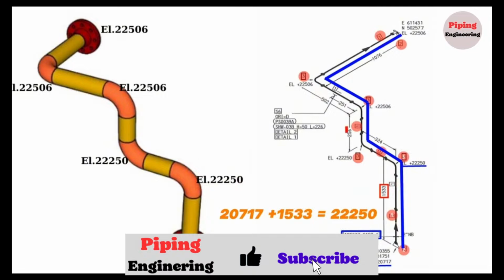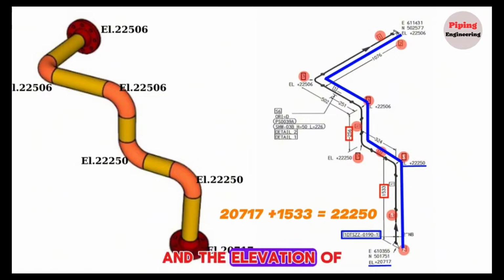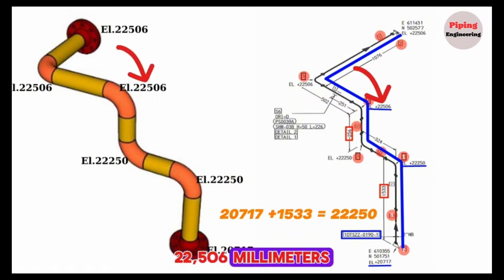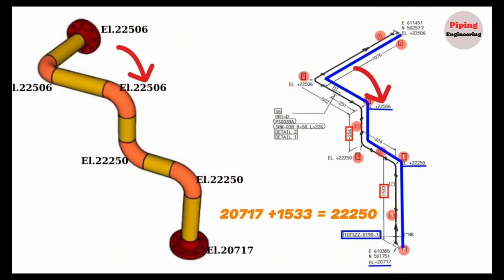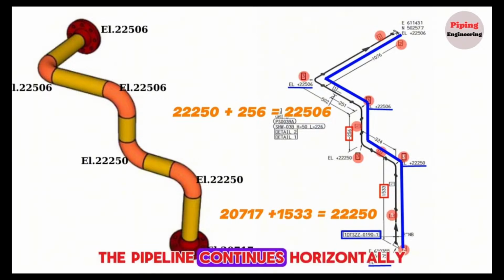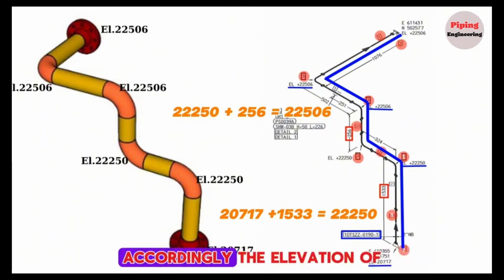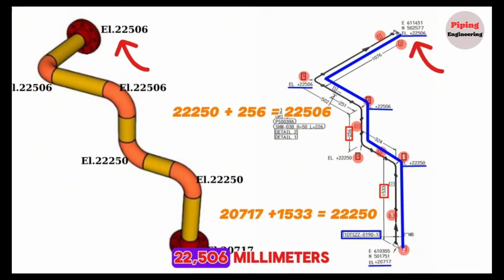Then the pipeline goes up 256 millimeters again at this point, and the elevation of this point is shown as 22,506 millimeters. We can easily check again the correctness of this elevation. 22250 plus 256 is 22,506 millimeters. After this elevation, the pipeline continues horizontally. Accordingly, the elevation of the last point will be 22,506 millimeters.